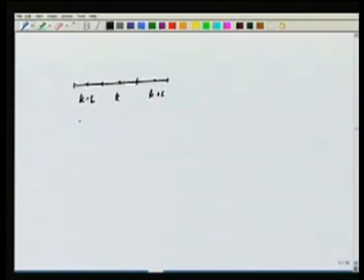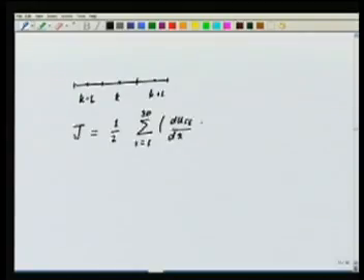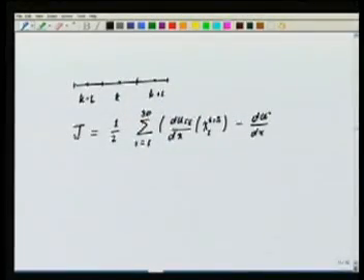What I am going to do is define this functional J as half the sum over all the i's, i equal to 1 to 3, actually it should be 3p, of (du_FE/dx evaluated at the point x1 i superconvergence minus du star/dx evaluated at the point x1 i superconvergence) whole squared. For us p is equal to 1.